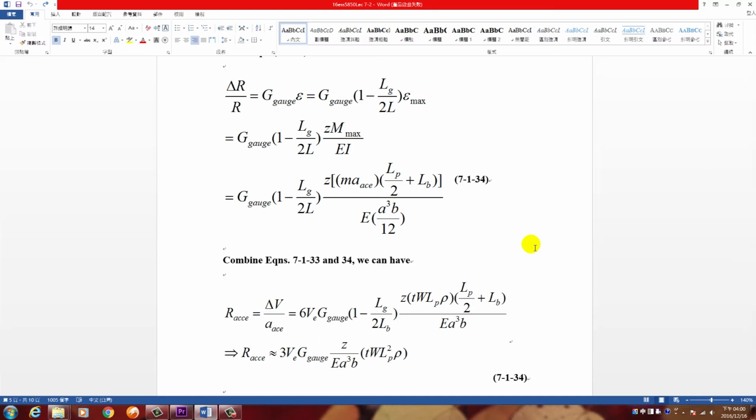So in your design, when you have selected the fabrication technology, for example, CMOS, it's not easy to change your gauge factor anymore because you already selected the material. For example, polysilicon, so the gauge factor will be fixed. When you select polysilicon, the Young's modulus is also fixed, and the resistivity depends on the doping level.